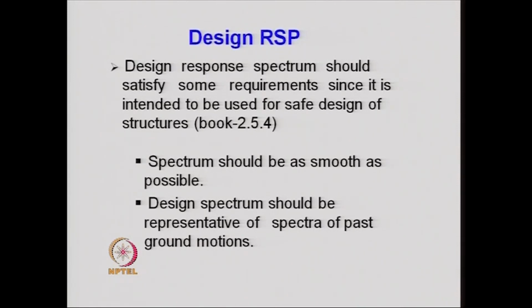Now let's come to the design response spectrum. The design response spectrum is the response spectrum which is used for designing all the structures for future earthquakes which are not known. Therefore, it's a difficult task. What generally is done for obtaining the quantities for future earthquakes is that we try to see the trend of the parameter that we are looking for, of that parameter in the previous earthquakes.